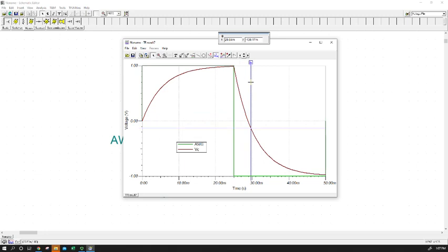So we're going to follow our V sub C, and what we're going to want is a voltage that is predicted by our calculated expression, our derived expression for voltage over the capacitor. So we're going to go back to the calculations we did in our earlier video, and I can't write them here, but I'll just verbalize them. We had come up with an expression that said the voltage over the capacitor at any time from this point here, where the capacitor is fully charged, and we're going to let it discharge and then charge up in the other direction. So the voltage at any point from this time is given by the amplitude of the imposed signal, which is 1 volt in this case, times negative 1 plus 2 times the exponent of negative t over RC, or negative t over tau.